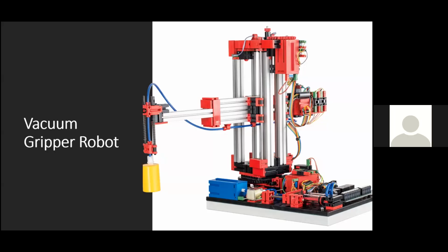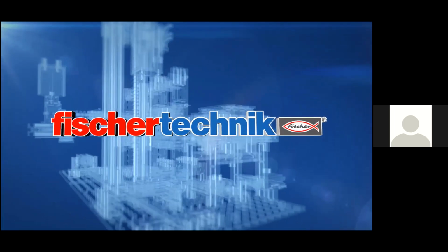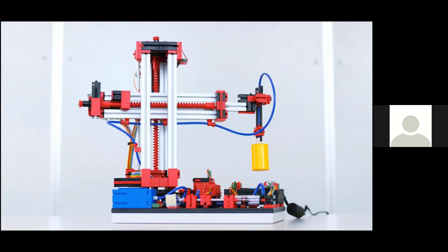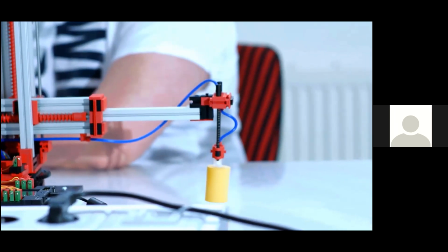The first model we are going to look at is the vacuum gripper robot. Now, as you're going to see in a second, the vacuum gripper robot is a 3-axis robotic model with a vacuum gripping device. The model is designed to precisely pick up and position workpieces in 3-dimensional space. The model includes 3 encoder motors, 3 push-button limit switches, a vacuum suction device, a compressor, which is the blue brick component that you see on the arm of the model in the video, and it includes a solenoid valve. The model's dimensions are approximately 9 by 19 by 15 inches and it has a weight of about 7 pounds.